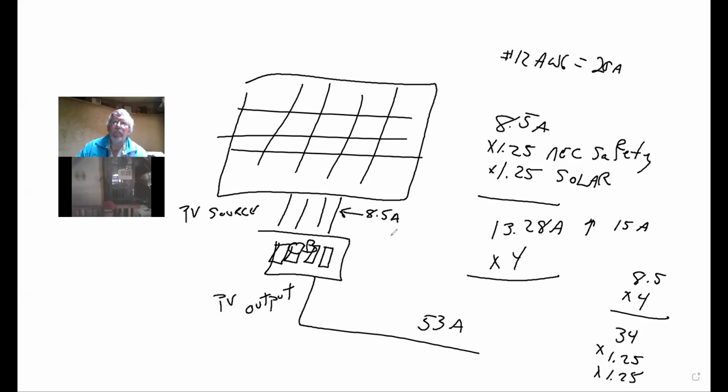One thing people get confused with is that making the adjustment for temperature does not change the number of amps that are flowing through the wires. So once you're back into a situation where temperature is not being affected by sunlight, the same number of amps are coming through. So you would go with a 15 amp breaker.